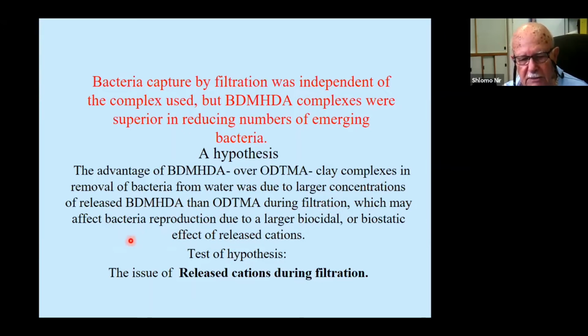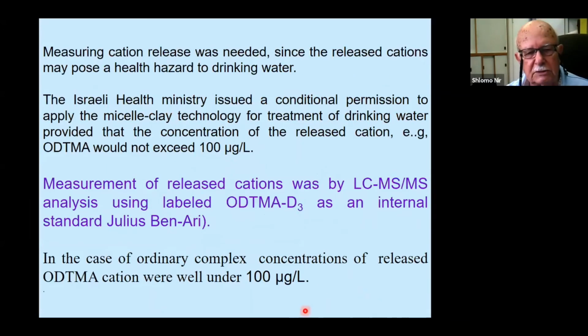The released cations can affect bacterial reproduction, the so-called biostatic effect, or killing, the biocidal effect. So this is the hypothesis, and we started to test it by measuring released cations during filtration.